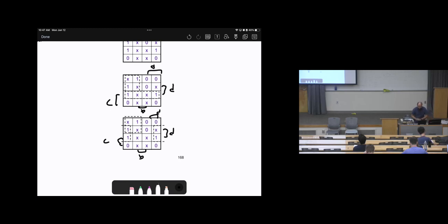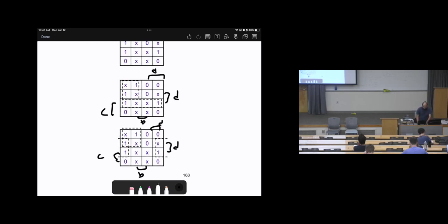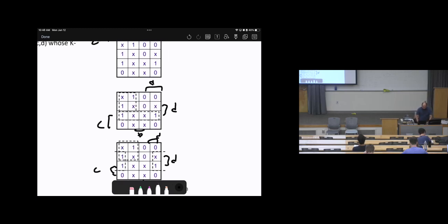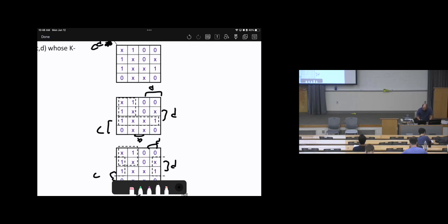Okay, so we can group this in different ways. Again, there are many solutions, so we have don't cares, so we can group these 4, then group these 4. So the answer F will be A bar, C bar, plus, this is the first loop, second loop, D and C.